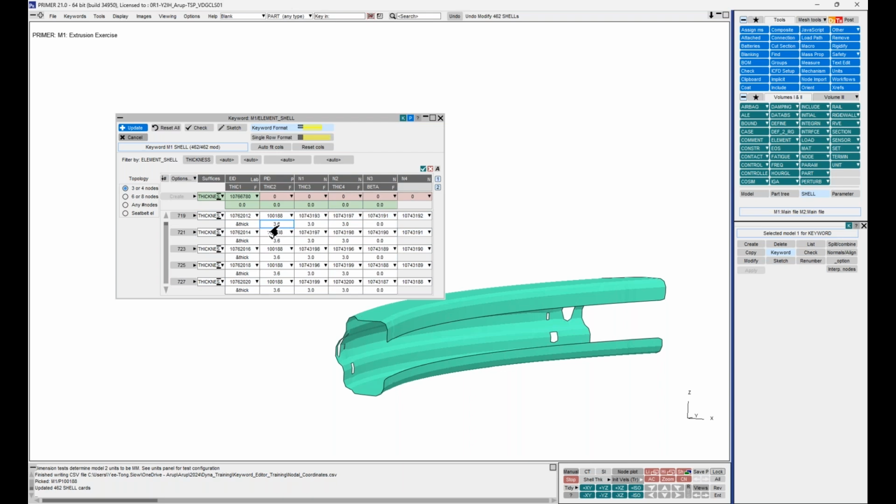You notice that when I made changes, for example, 3 times 1.2, this reflects onto all of the other rows. I'm going to show a demonstration now. If I change, for example, node 2 and 3 to 2, what's going to happen? If I go select all again, and the same thing here, if I go to equals 2 multiplied by 1.2, you can see that even though this is 3, it gets updated by the row that I was editing, which is not really what we want sometimes.